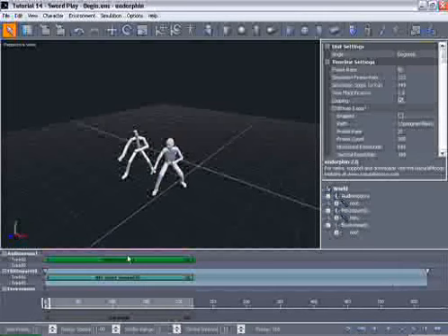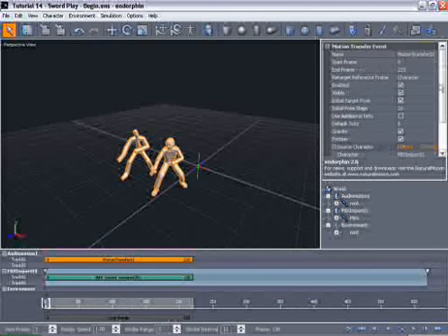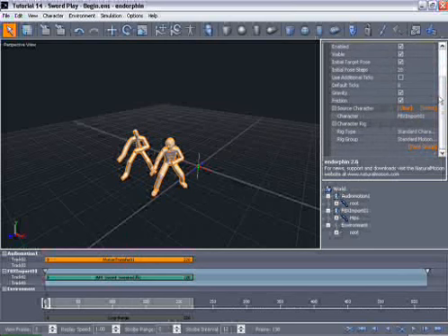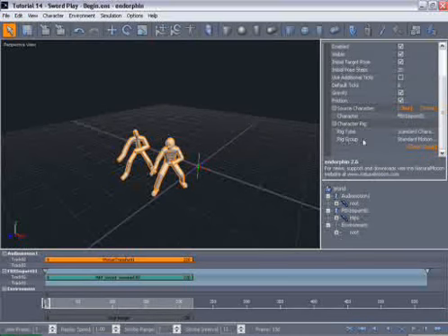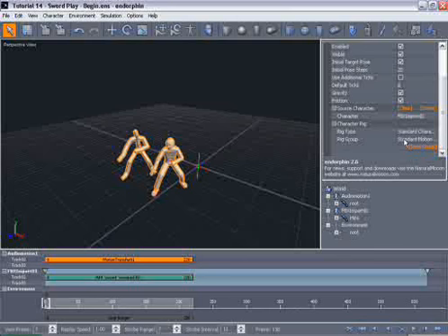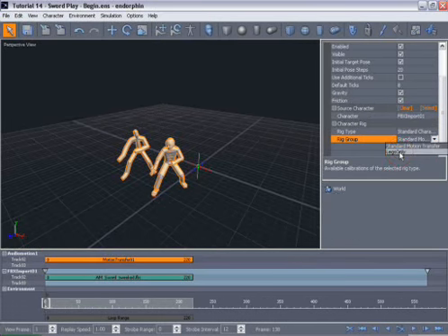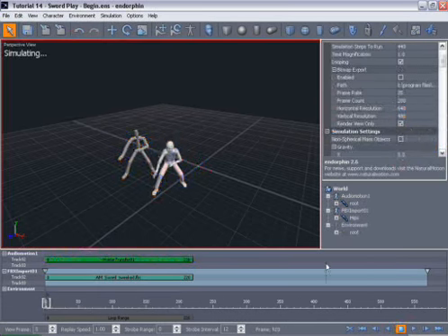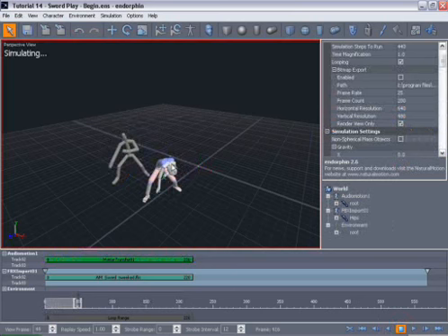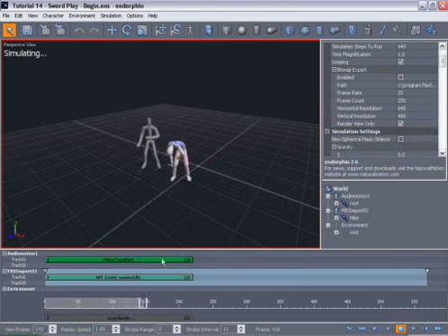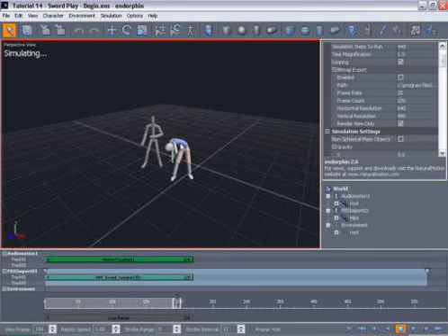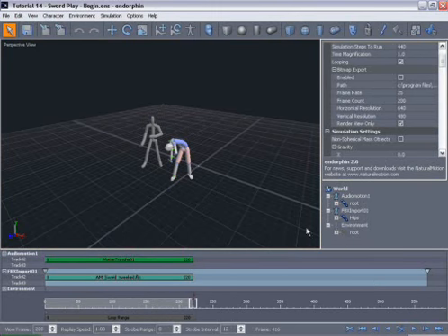Now back in the scene, if we select the motion transfer event and move to its property view, scroll down to the bottom, you'll see that under character rig there's a rig group of standard motion transfer currently selected. We click on that, we'll see that our new legs only rig node group is also available for selection, so pick that now. And now when we simulate, you can see that the top half of our simulation character's body simply flops around, and that's because the motion transfer event no longer has full control of the top half of the body because of the settings we put in the legs only rig node group.